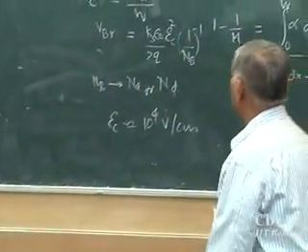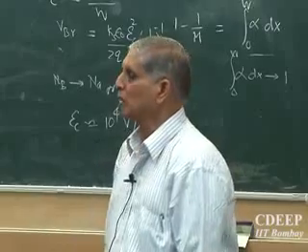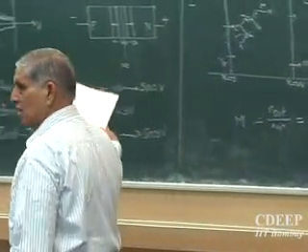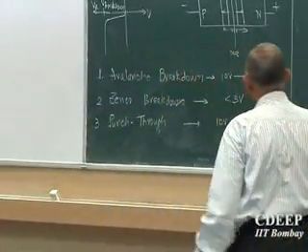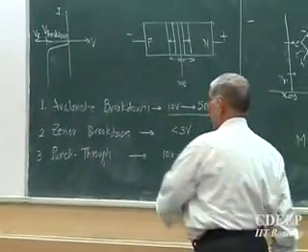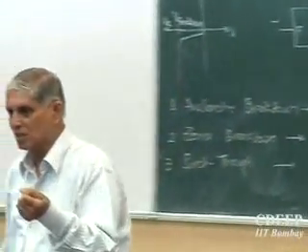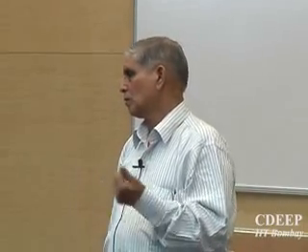At this electric field, depending on the doping, one may get the breakdown values. Is that clear? So these numbers are decided by what? The base concentration I choose will decide my avalanche breakdown value. Is that correct? Whatever N or NA or ND I use for the base may decide the value of breakdown.